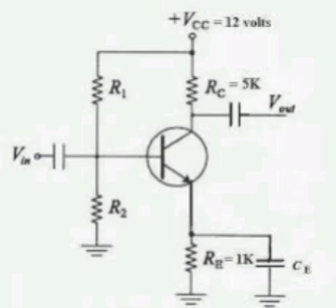Again parallel ZL between A and B. The condition for maximum power transfer in the circuit is ZL equals ZTH conjugate. So we can write it as 5 ohms parallel with 20 ohms in series with j3 ohms in parallel with minus j6 ohms. That is nothing but Z Thevenin. Z Thevenin equal to 5 parallel 20 plus j3 whole parallel minus j6. ZTH equal to 4 plus j3 into minus j6 whole by 4 plus j3 minus j6, which is 5.76 minus j1.68 ohms.